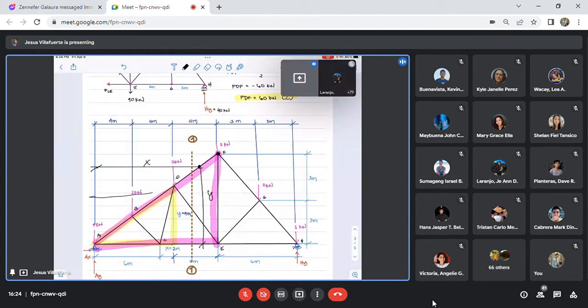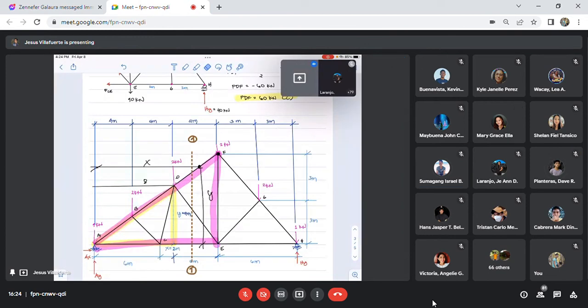If we put it here at point D, we know that this is 8 and this one is 4. Right? So you know already. You have to locate your vertical and horizontal components at a point where you know your moment arm, so when you take moments, it is easy. Do you get my point, class? Yes, sir.